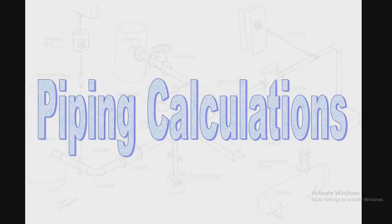Piping calculations. Piping calculations related to design. If we work on power plant projects, we will use design code ASME B31.1. If we work on process piping, we will work on design code ASME B31.3 for process piping. So the piping calculations related to the designer, according to design, are related to material selection, piping size, schedule or thickness.